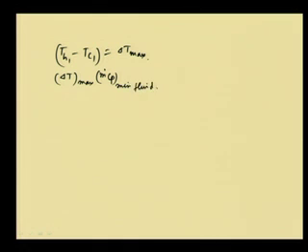That is understandable. So, the minimum fluid only can go to the maximum temperature difference, the other fluid cannot go that much temperature difference, because otherwise it would violate the law of thermodynamics. So, the total heat exchange from one to the other will remain the same. Therefore, if m dot Cp is the minimum fluid, then m dot Cp into delta T maximum is actually the maximum possible heat transfer.